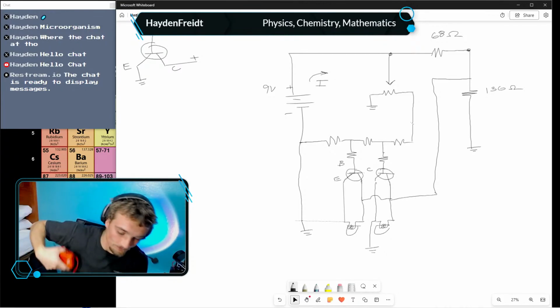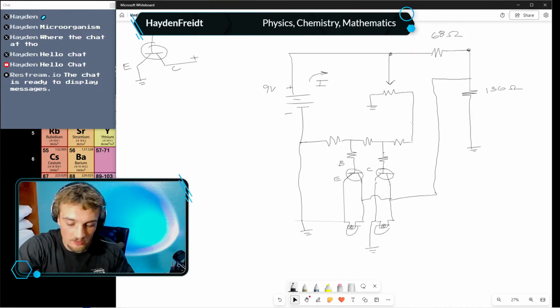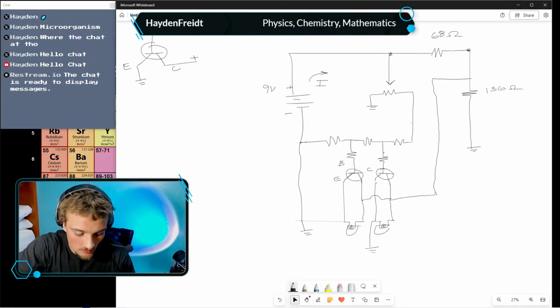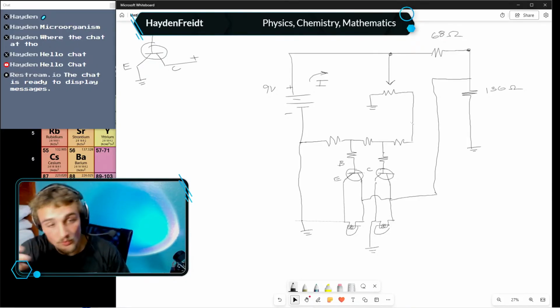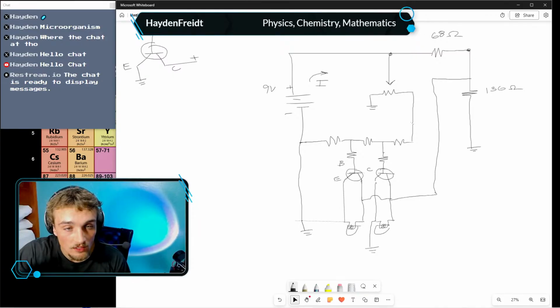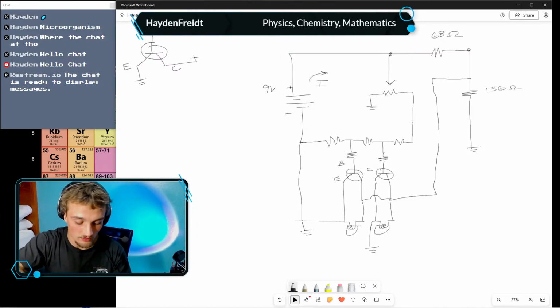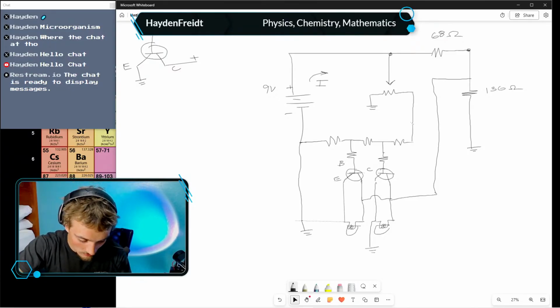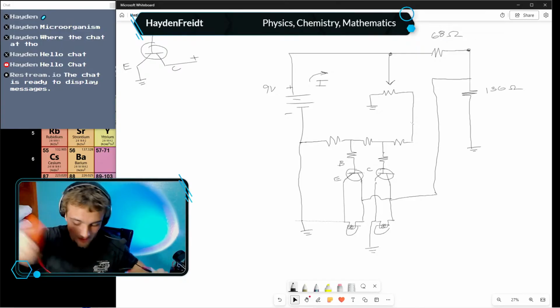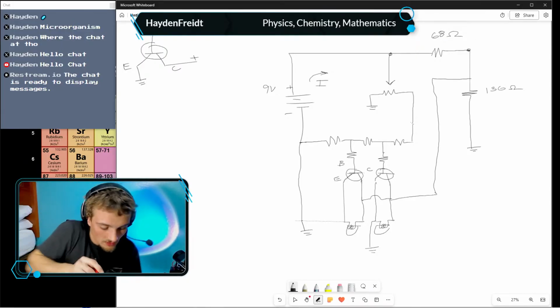Okay, so I'm just going to use the multimeter to directly measure the ohms. Otherwise, we could look at a color diagram for four-band resistors, but I don't want to do that. It takes too long. Alright, so we're going to set it to 2 kilo ohms and I'm just going to go through and measure these.